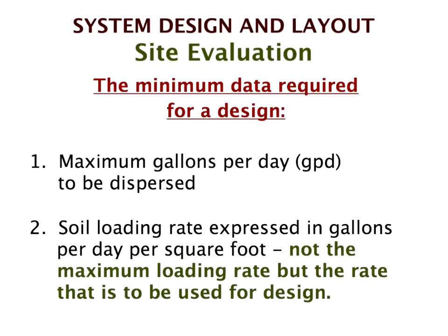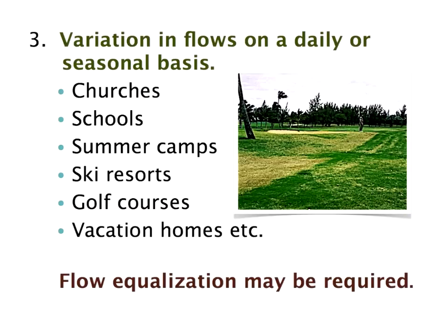Obviously, you need a maximum gallons per day. Not the average, you need the maximum gallons per day. You need the soil loading rate expressed in gallons per day per square foot. Not the maximum loading rate, but the rate that's actually going to be used. You need the variations in flow on a daily or seasonal basis.